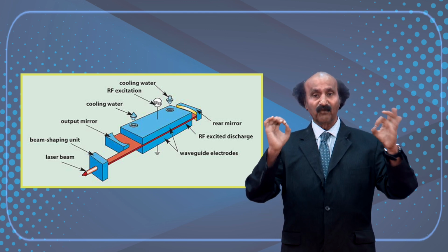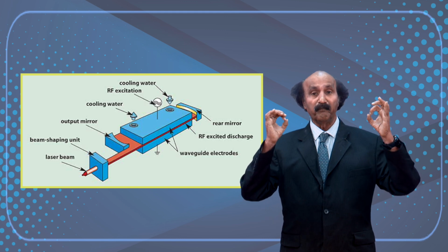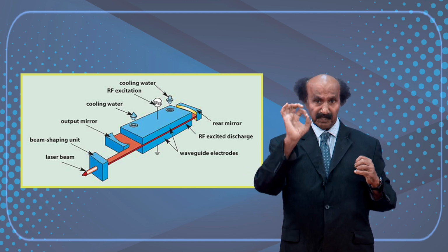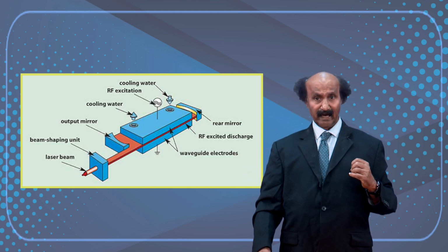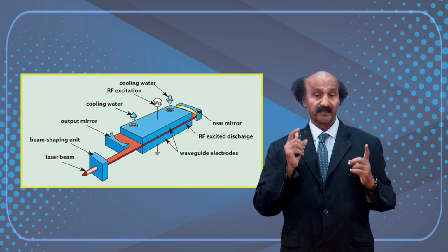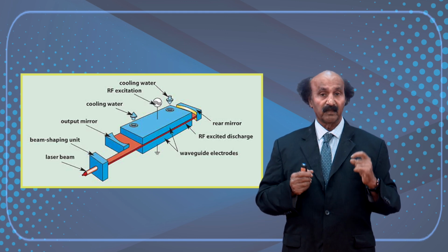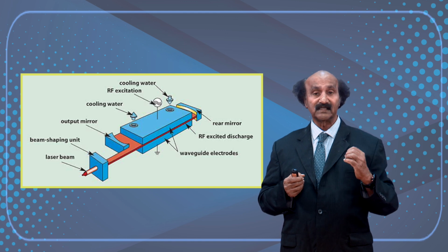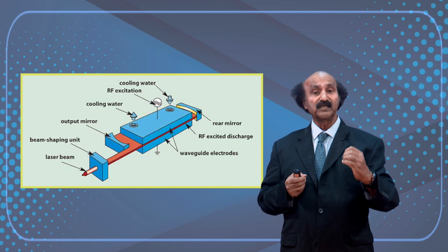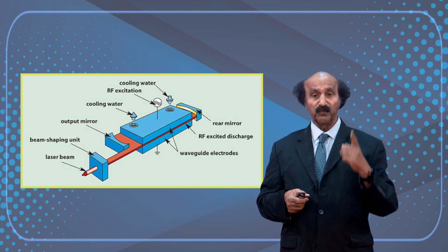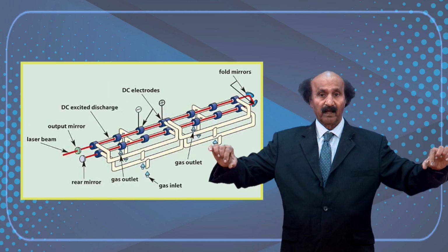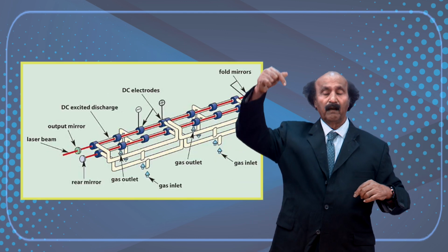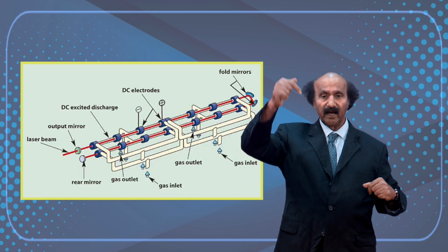Then what you do, you keep on applying voltage. At a certain voltage, there will be a breakdown because the potential at the tip of the electrode, watch out, these are all pointed electrodes, the potential at the tip of the electrode will be very high, such that it produces an intense discharge between the long rod anode and the pointed negative electrode.